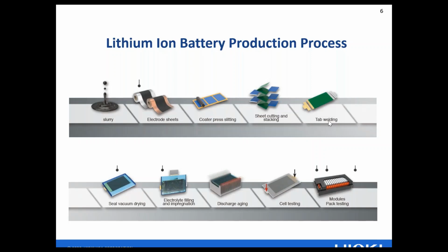That's a whole different topic of testing. We can talk about that in one of the next seminars. Just the welding and making sure that you have good contact, and talking about milliohms and maybe microohms, can be very important. The cells are vacuum sealed and dried. Next step is to fill the building blocks with electrolyte. That's when the batteries actually become operational. They get discharged and cycled and aged before they actually hit the shelf.